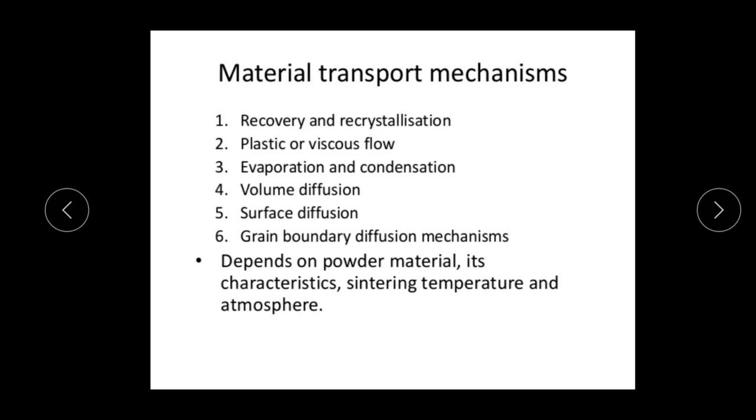In material transport mechanisms, we will discuss recovery and recrystallization, plastic or viscous flow, evaporation and condensation, volume diffusion, surface diffusion, as well as grain boundary diffusion mechanisms. All these mechanisms depend on powder materials, their characteristics, sintering temperature and atmosphere.